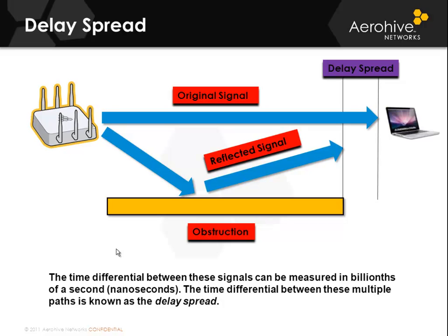But unlike 802.11n's use of MIMO, Cisco devices strictly use this for diversity. Whichever antenna receives a stronger signal, that signal will be believed, and the other signal will be discarded. The signal usually arrives via multiple paths and with different angles of arrival. The time difference between the arrival moment of the first multipath component, which is normally the line of sight component, and the last one is called the delay spread.